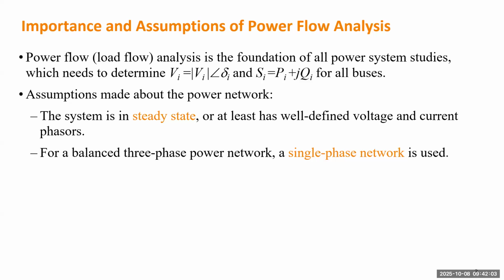The transformation from the 3-phase network A, B, and C to the sequence network is accurate. So you still can use power flow analysis on each sequence network, for the positive, negative, or zero. They will give you some indication about what the post-fault system can be. Even if it's maybe not 100% accurate, it's still very useful.